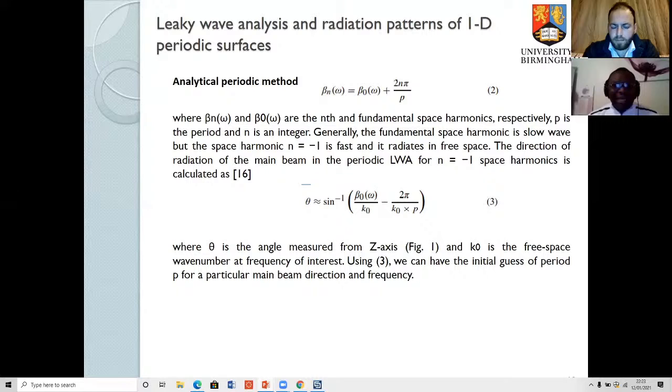If I take 51 gigahertz and take its wave number and put it into the equation and scan the beam, I will know the angle at which this particular frequency will be, and so forth and so on. So if I take 50, 51, 52, 53, and so forth to 66.